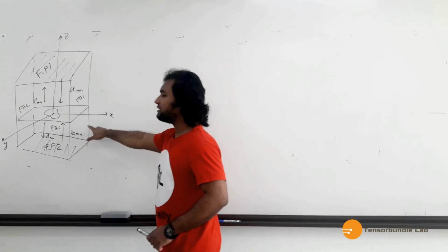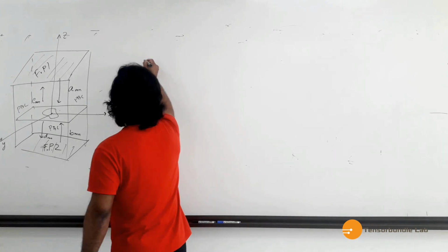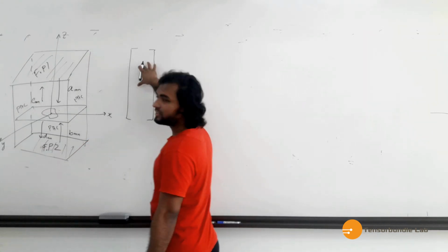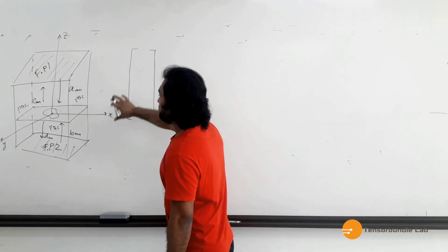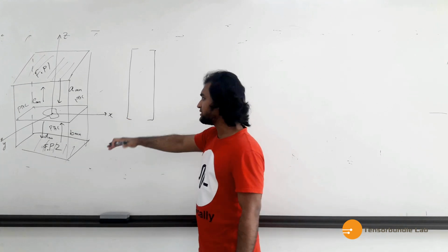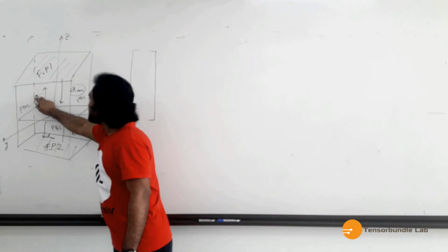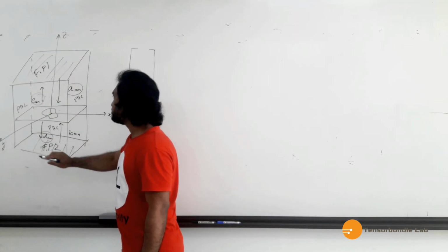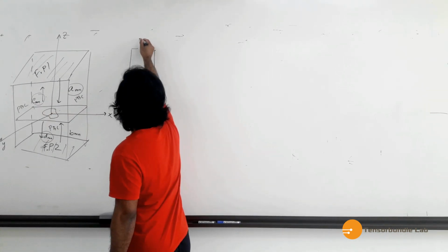So if you write down the scattering matrix equation for this system, we can say these are the reflected waves or the scattered waves or the scattered wave vectors. And there will be transverse electric and transverse magnetic modes associated with the incident and the scattered wave. The scattered waves are C in port 1 and D in port 2. So let's write C first for port 1. This is the scattered wave.